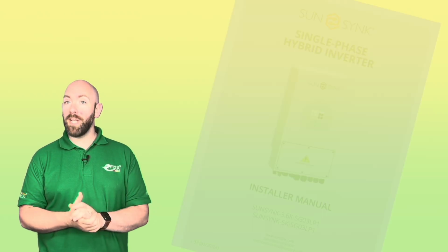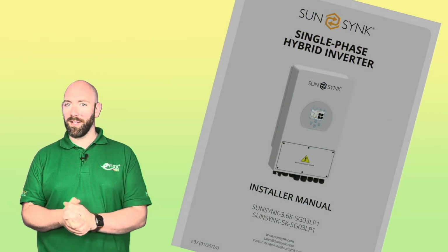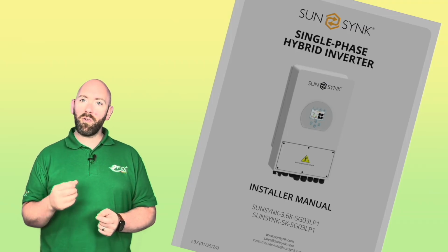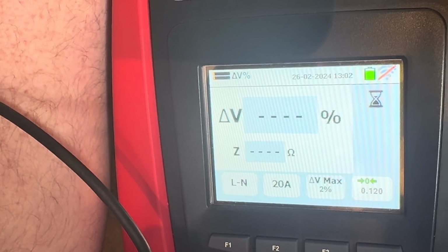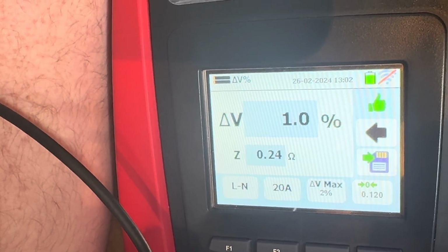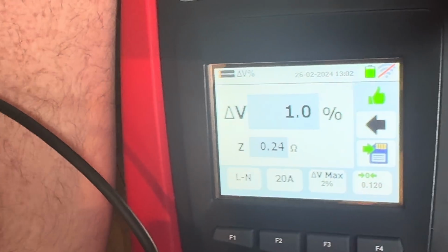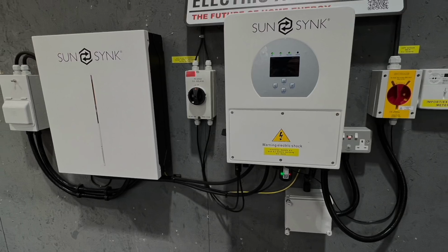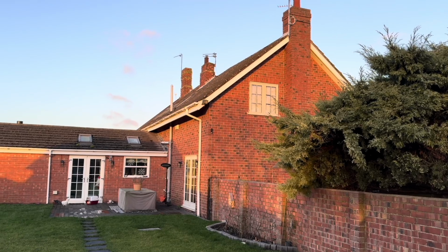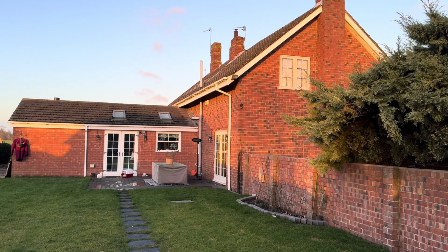So what can we do? The manufacturers will all offer guidance as to what the voltage ranges of the inverters are and if the volt drop is acceptable. As we're using the Sunsynk inverter, I contacted them and they said that the volt drop for the 4mm squared cable is okay for the inverter as they use the 1% as a worst case scenario. It's food for thought though, certainly on some of the longer cable runs to inverters that are out there.